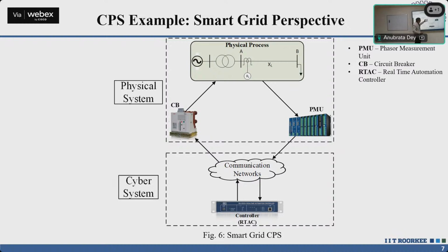Now if we consider the example of our power system network, then we have some network, maybe IEEE 14 bus or 30 bus or a higher one, and you have installed several synchrophasor devices, let's say PMUs, at different locations, and then they acquire the data and pass it on through some communication network to the higher hierarchical level.